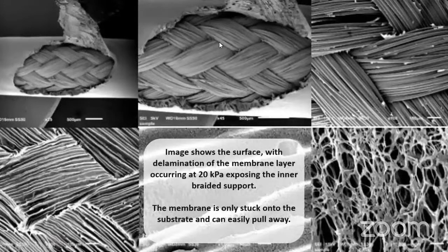So having a very strong fiber doesn't really help. The fiber is able to handle the high pressure or mechanical conditions, but the filter area is not able to handle them. This is food for thought. When you're selecting the filter material, one must take care that there is no chance that the laminate is going to get removed.